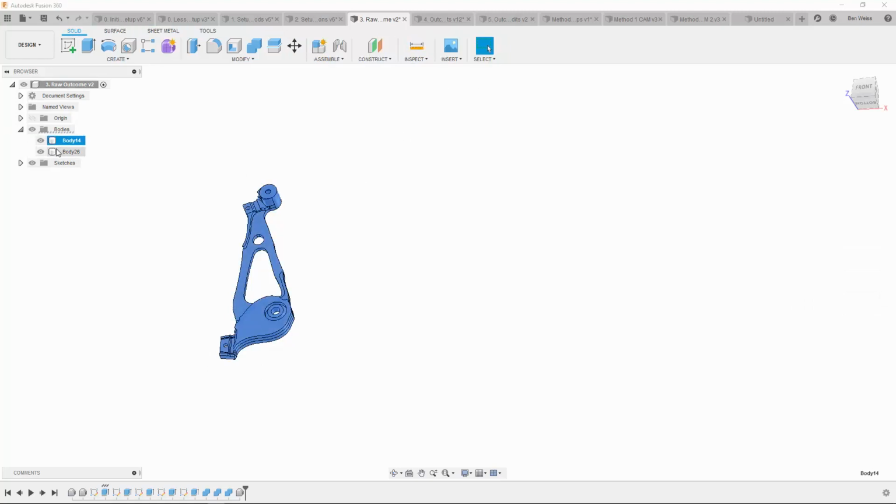Now if we look in our tree, we can see that we have two different models that are just perfectly overlapping because I haven't made any changes to the sketches yet. The second one, though, is from the base feature object, and because it's historyless, I can move it all the way back to the beginning of the design. I'll also rename it Original Shape so that it's easy to refer to later. Okay, now let's move back and pick up where I left off.